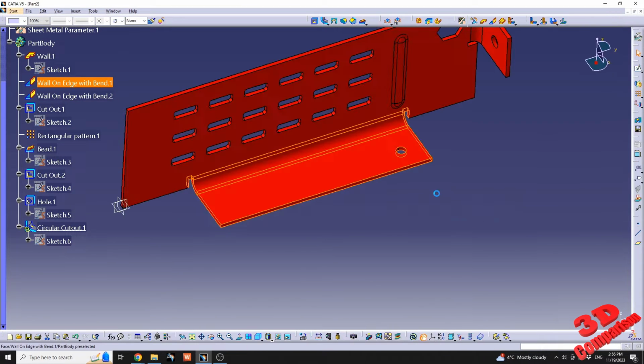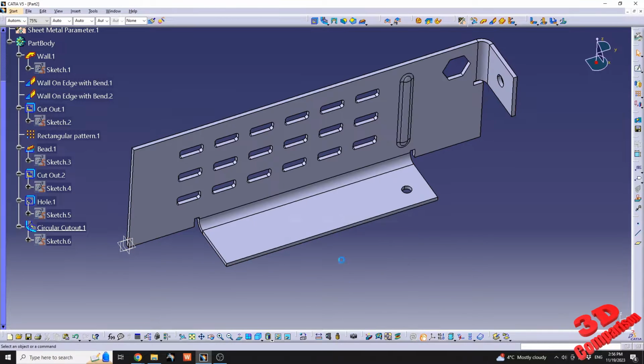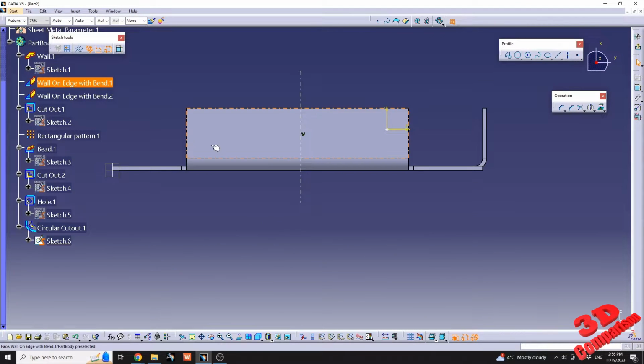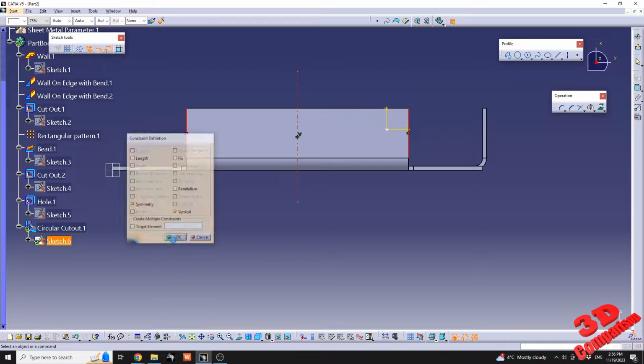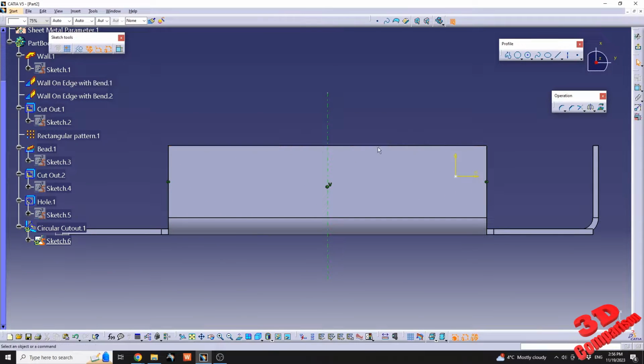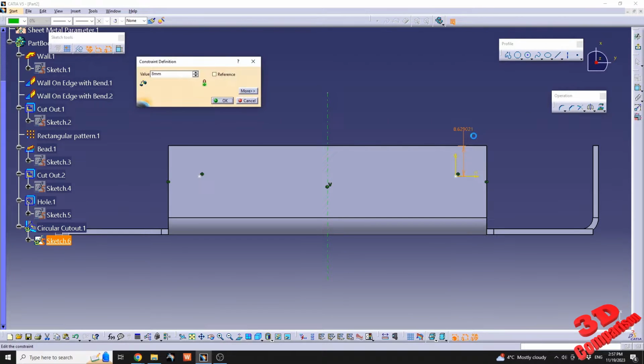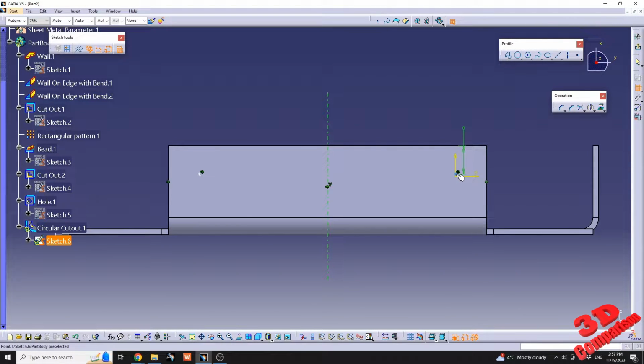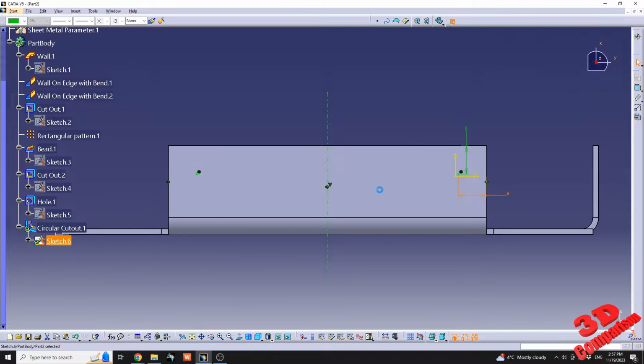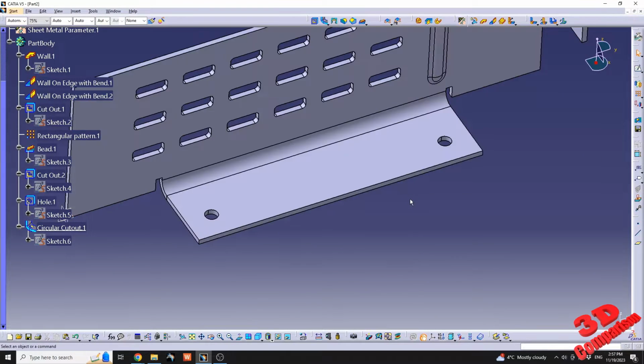So I will do that selection again, because the mouse sometimes, when I only want to click once, does a double click, so this is quite annoying in CATIA. So we have that mirror line, we have the point, and we can have that mirror around. And now if I change the value over here, maybe I'll position this to 8 millimeters from the side and to 8 over here, the mirror will also be positioned, and afterwards we have this mirror.